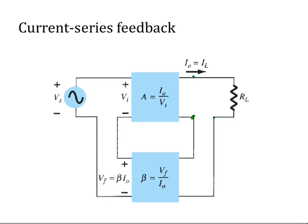Current is flowing in the circuit like this. So current is taken as feedback, and beta is again the gain of the feedback network, and it is connected in series. So of course you will have a voltage. So Vf is equal to beta times I0, the current which is fed back. So beta I0 or Vf is connected in series with the input voltage. So it is current series feedback.